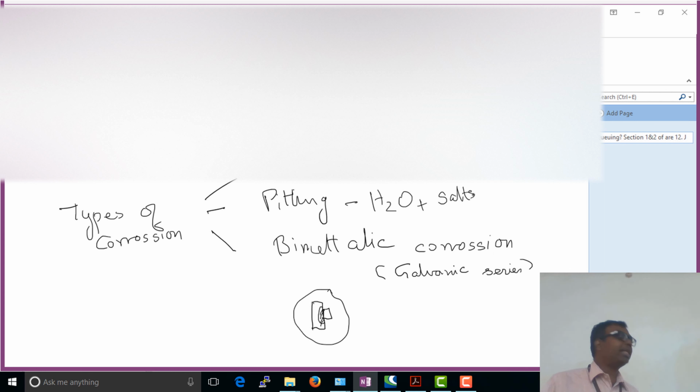Okay, so pitting corrosion is also a little inevitable because we've got steel piles which are there in the sea. You may have alternate wetting and drying cycles which are inevitable. So for this, usually we go for the cathodic protection systems. It means that as a structural engineer, you should know that this is an option available to you to protect, because there is only so much you can do with coatings. Okay, the coating can break and that is more dangerous.